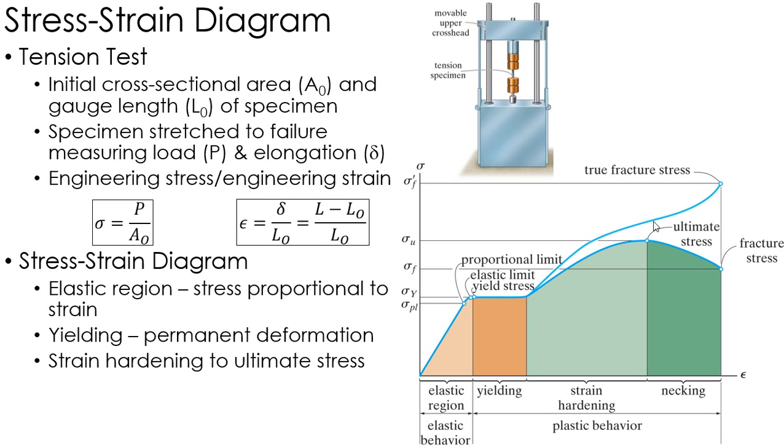Because after that ultimate stress, that very high stress and the strain hardening, what I get is necking. I don't have a picture of this, but you can check your book. It's basically a localized area decrease, where it just kind of pinches off in one location. The area shrinks greatly, and basically you are on your way to failure. And you can see actually, the area is decreasing so much that my stress doesn't actually increase. Once I hit that ultimate stress and necking occurs, we're in trouble. This thing is going to fail.